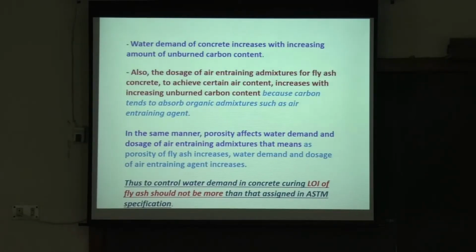Water demand of concrete increases with increasing amount of unburnt carbon content. Now, the dosage of air entraining admixtures in fly ash concrete increases with increasing unburnt carbon content. So if you have more unburnt content, meaning LOI is high, some of these things are worth keeping in mind. Why does it happen?